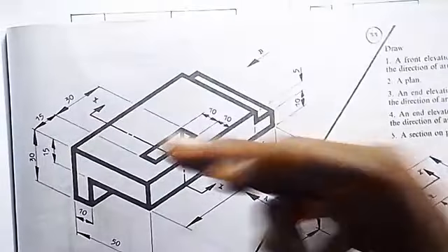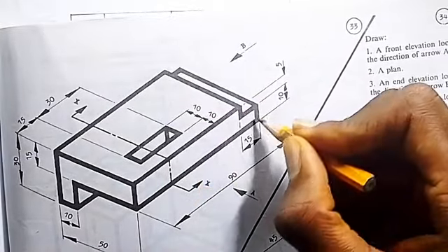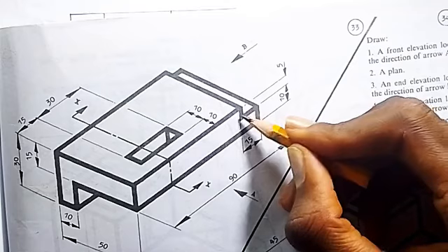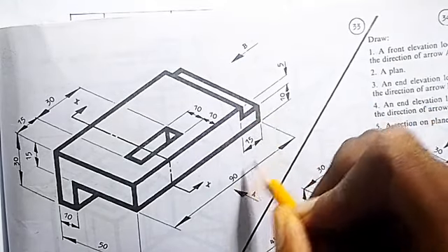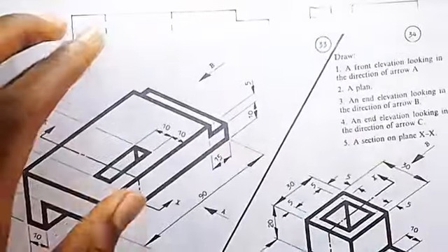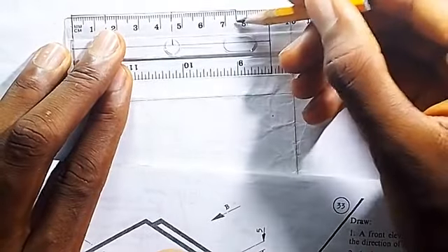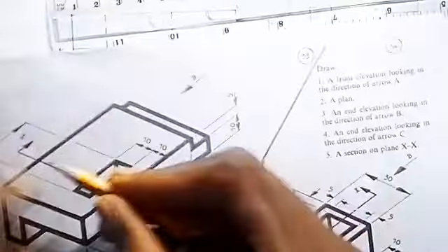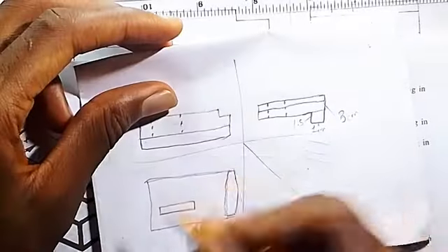So at the top of plan, what do we also have? After the block, we have this rectangle, total length. Remember, here is 1.5 for this top part. It's now 9 cm because it came down. So 9 minus 1.5 is giving us 7.5, because this is this part. So the length of this first part is 7.5. Then we extend it by 1.5, the rectangle. So let's draw that.